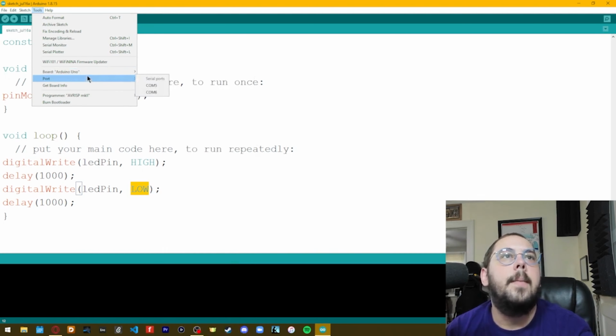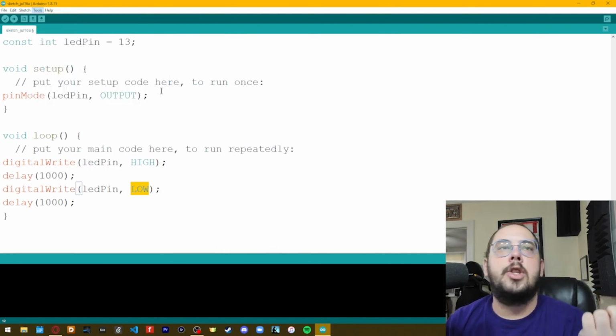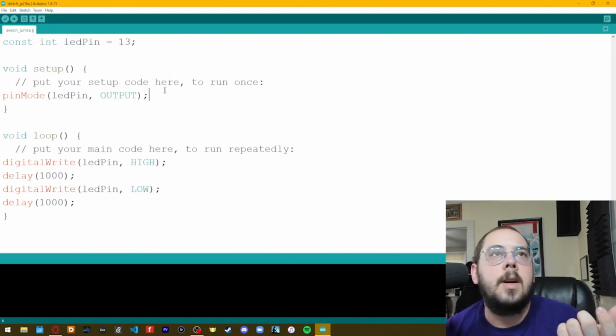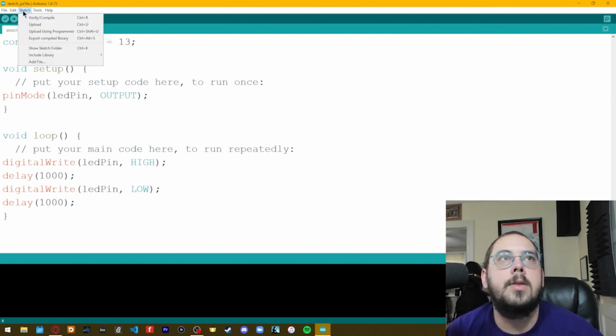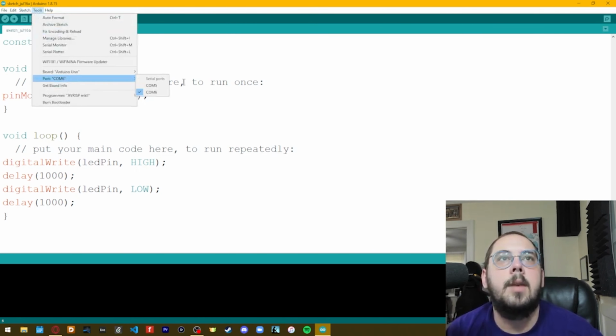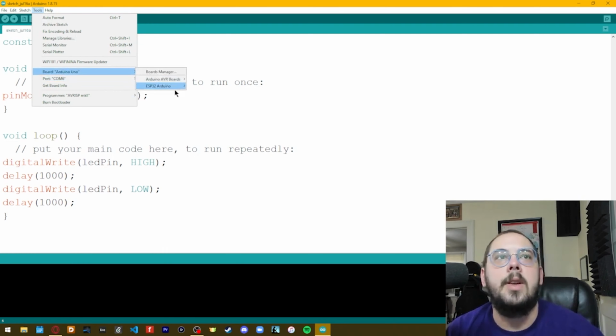manager here. But then under Port, once you've connected it, you should see a port, and it'll be labeled with Arduino Uno. As I'm recording just the code video, I don't have that plugged in right this second, but in just a moment we will. But anyways, you'll see that there. If you're on a Mac and not a Windows device, it won't say COM6. It has some big long name, but it'll still say in parentheses afterwards, Arduino Uno, and that's the one you want to select.